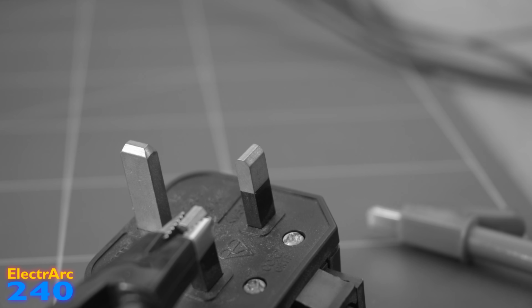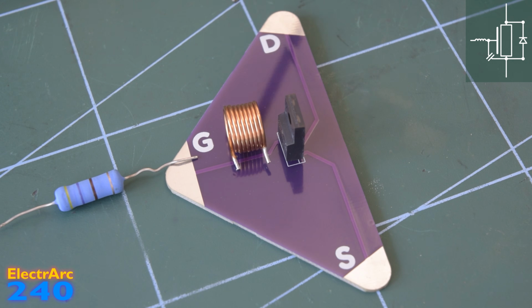So, as we've seen in my previous video, now let's look at both together. What we get is a high voltage arc between the positive connector and the inductor, and this is thousands of volts, and is actually quite dangerous. Not only to people, but more importantly to circuitry. If the current passing through an inductor changes very quickly, the inductor itself will generate a large voltage in an attempt to keep the current the same. Even though these parasitic inductances on a MOSFET are typically in the order of nanohenry, the rate of change of current is so high that there can still be a significant voltage generated.